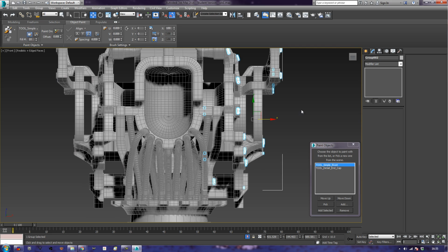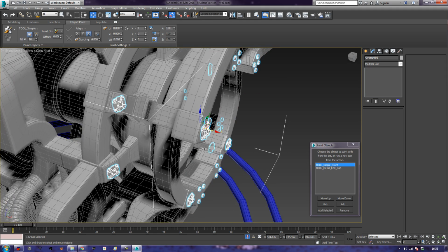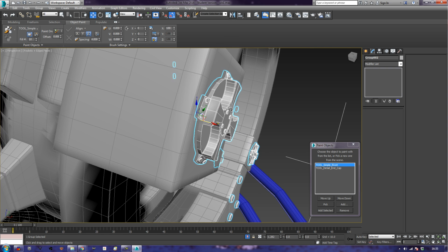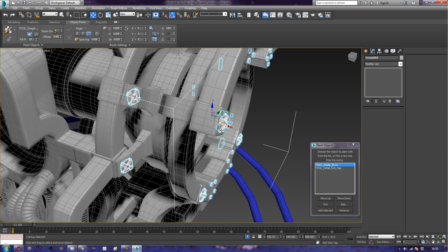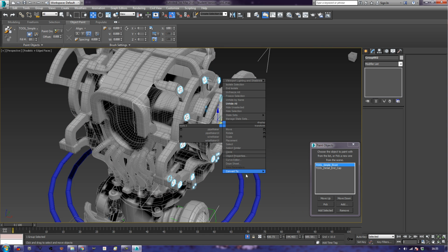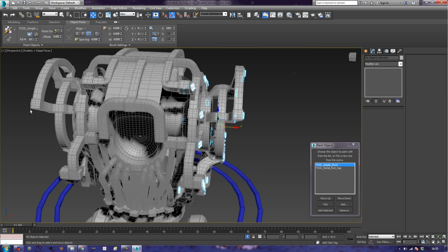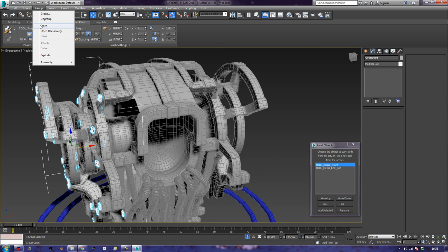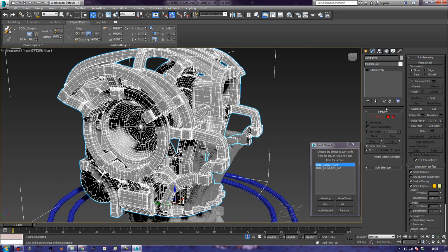Okay, so let's have a look over here, just make sure there's no gaps. Gaps are the devil's work. Okay, just check that, that's fine. Okay, that's cool. Now if I right click convert to editable poly incidentally, you'll notice it is still a group. That's okay. Now I'll go over here and get this group. Ungroup. There we go. This will make attaching these things a lot easier though, because now I can attach them all to this unit.